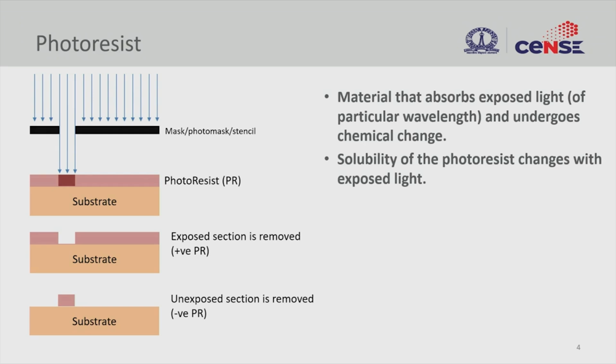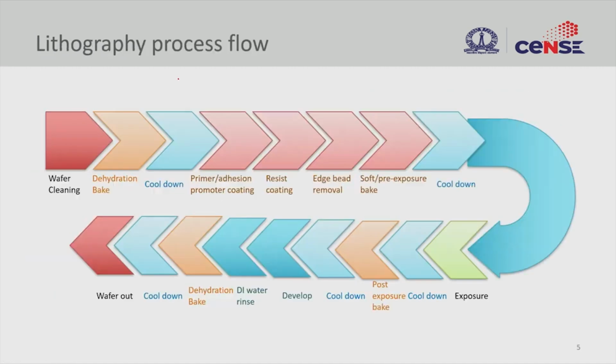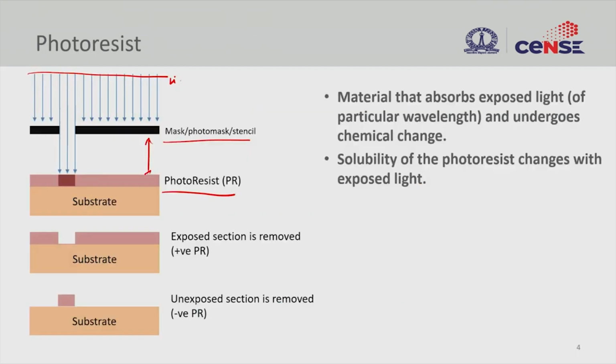And on the wafer, we have a photoresist that is spin coated, which we saw earlier, and then the mask is placed with a gap or on contact. It doesn't really matter. Here, for illustration purposes, we are just using a gap. And we are putting a uniform light source. So this is light falling onto this mask, and we have transparent and opaque regions here.